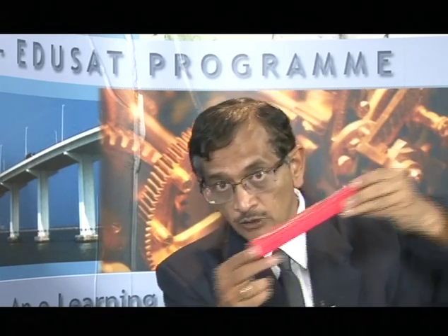Yes, you are right, it is on an incline with an angle of 30 degrees. So as I mentioned in the previous explanation, W sin theta will be responsible for movement, correct? What is W? It is 0.45 kN. What is theta? It is 30 degrees. So 0.45 into sin 30 will be responsible for motion down the inclined plane. Is it okay? Let us continue.